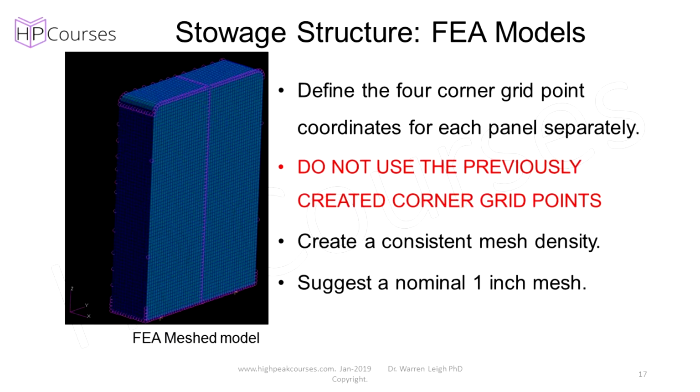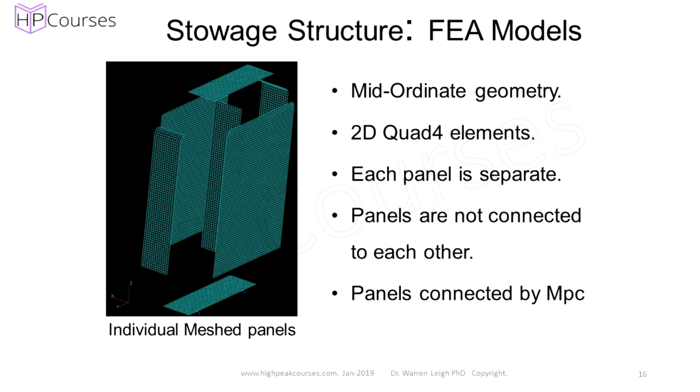To summarise, this is a 2D mid-ordinate finite element model, constructed in either Femap or Patran. Each panel is independent of the adjacent panel. Each panel is connected to the adjacent panel by MPC elements.